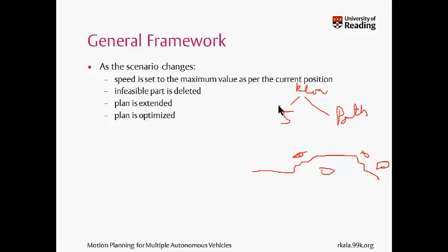So I need to simultaneously work over speed and path, and we know that from an optimization perspective that's impossible to do. That's a very computationally expensive task. My path depends on my speed, which depends on my path. If I work on both simultaneously, it becomes a very difficult planning problem. So I simply divide these two problems. I'll say let us take speed separate and let us take path separate. Let me first fix the speed, and for this speed I'll calculate the path.